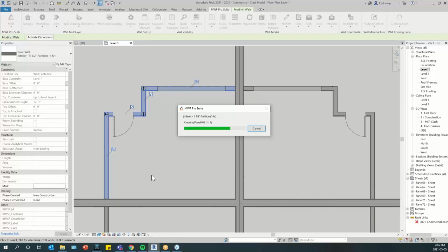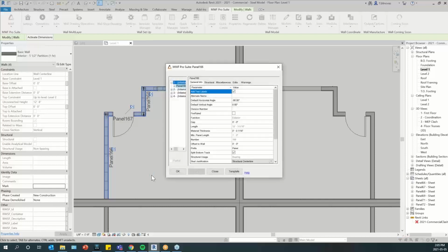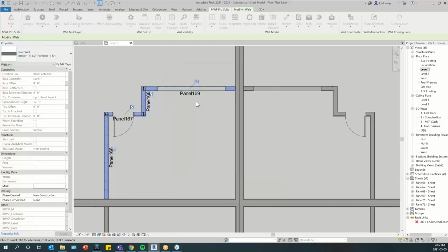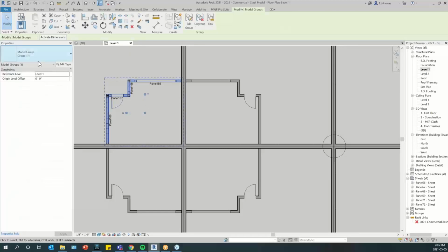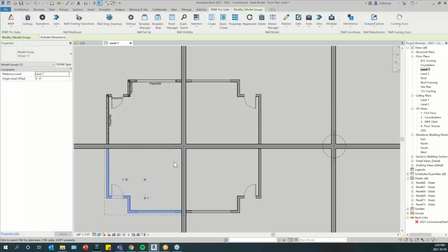We're first going to go over the first option that we have under modular tool, which is create panels on all identical groups. So there you go. Now I have my panels. And then what I want to do is push these panels to my other groups here. And they are all identical groups. So if I, again, select my group here, this is group 1.1. These are the same. So they are identical. It's very important. It will push the changes only to the same group. So it has to have the same name. So it would have the same panels, okay?